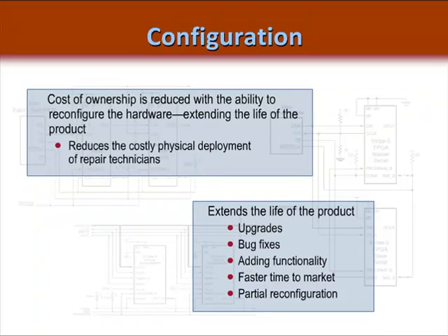Now this might allow a smaller FPGA to be used since the buffer could be reprogrammed quickly from an external memory source, and only the buffer that was needed at the time would have to be programmed into the FPGA. While partial reconfiguration is a very cutting-edge technology, it is not necessarily suitable for many customers. It is fascinating, and hopefully this example gives you an idea of what partial reconfiguration means.